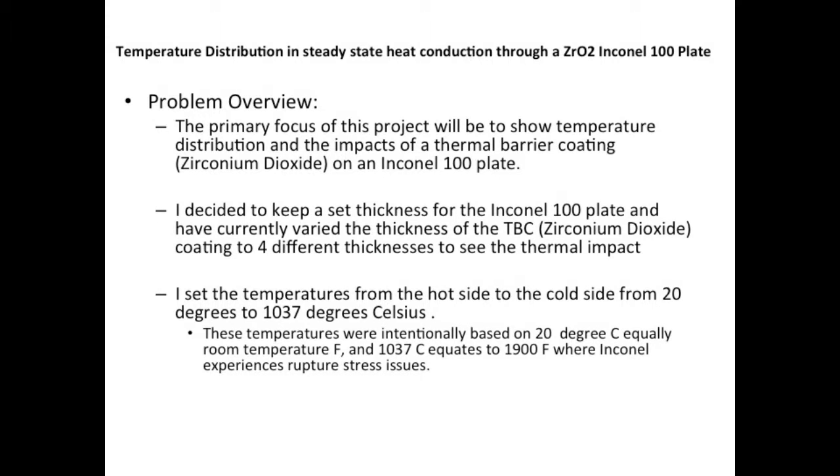The primary focus of this project will be to show the temperature distribution and the impacts of the thermal barrier coating, the zirconium dioxide, on an Inconel 100 plate. I've decided to set the thickness of the Inconel 100 plate as a constant and then currently vary the thickness for the zirconium dioxide to 4 different values and see the thermal effects of that.